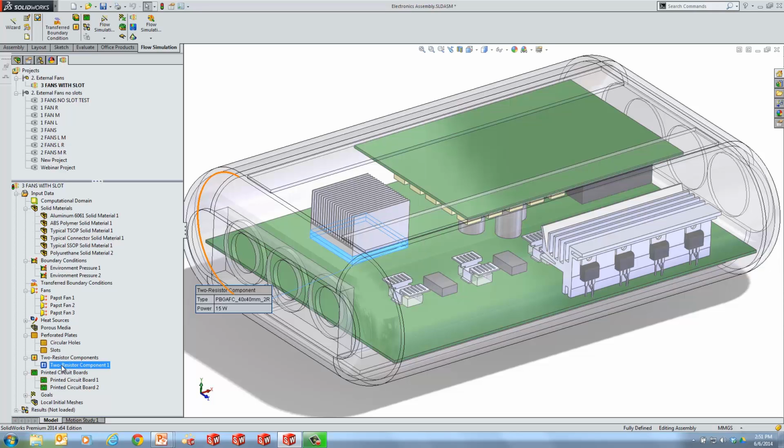A small package is considered as consisting of two flat solid plates, junction and case, which are mounted on the board. The junction represents a die or chip. The case represents the die's case. The heat conduction through the chip is calculated using specified thermal resistances to heat conduction from junction to case and from junction to board. The junction and case plates are mounted as high conductivity bodies with heat insulating sidewalls, so only the case's top and the junction's bottom transfer heat to the surroundings. So that's something that you get with the electronic cooling module.